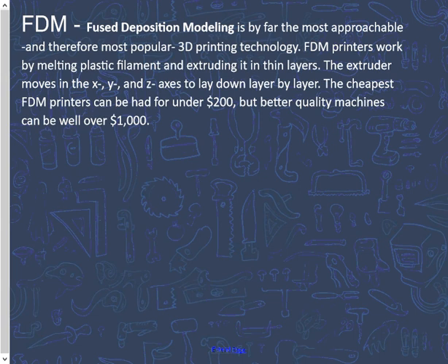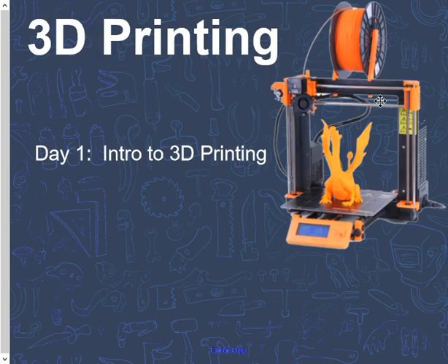So the X axis is going to be the side to side. So on our printer, if you can picture, let's go back to the front here real quick. This is the same printer we have. So this is the X axis, moving side to side. This is the extruder right here. There's some other parts there we'll talk about, but it slides back and forth on these two rails being pulled by a motor. This top black box is a motor, and it's hard to see in this picture, but there's a rubber belt going back and forth that pulls the extruder along this x-axis.